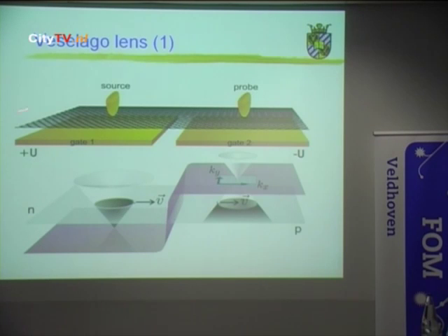So what I also have is the energy diagram of the system. This is the Fermi energy. You should realize, of course, that the system is in equilibrium, so the Fermi energy is like a sea, the Fermi sea is always the same. But I have attracted electrons here. That basically means that I have pulled down all the energy levels.